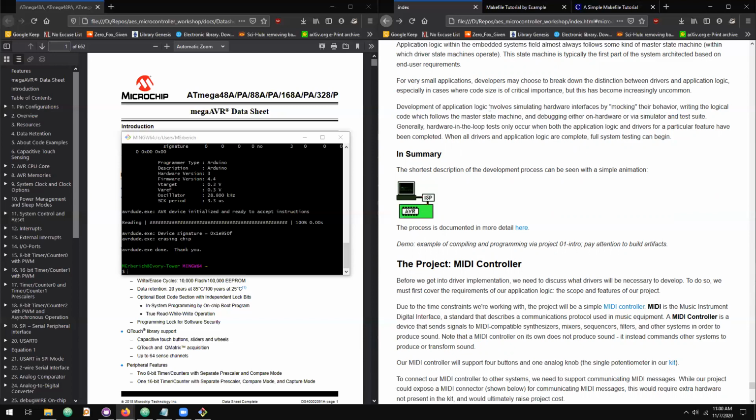And in order to simulate a hardware interface, all we need to do is make sure that the C implementation of that driver is in fact a stub, something that doesn't actually talk to hardware, but behaves at the interface as if you have communicated with hardware. We're not going to do this because I've already debugged the application logic and drivers for you. But there are certain software development techniques that can be useful in basically testing what you've written.